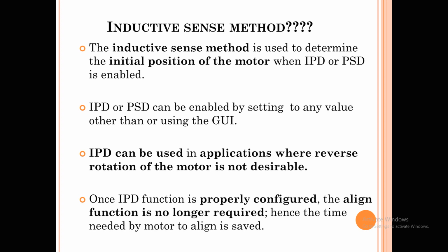When these features, IPD or PSD, are enabled, what does it actually mean? Before starting the motor, first we need to know where exactly the rotor position is aligned. Once we know that position, we energize the motor with the sequence of phases in such a way that the motor will start perfectly.